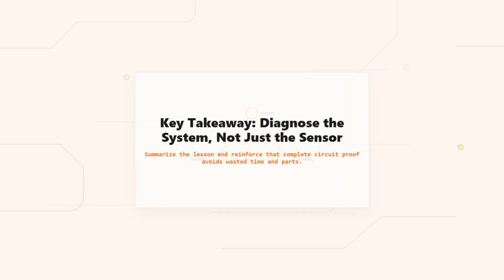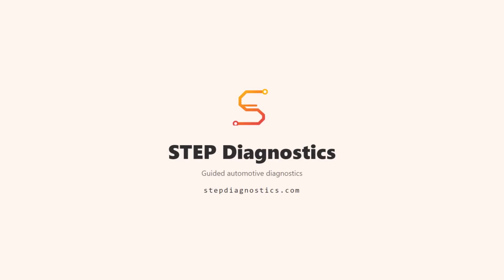Sensor circuits are 3-part systems. Diagnosing only supply, ground, or signal in isolation leads to trapdoors and wasted time. Always test, compare, and prove each leg to quickly find and fix the real cause. In every diagnostic, remember, scan data, direct measurement, and circuit logic must work together to reveal supply, signal, or ground faults. Keep testing, not guessing, for reliable repairs.